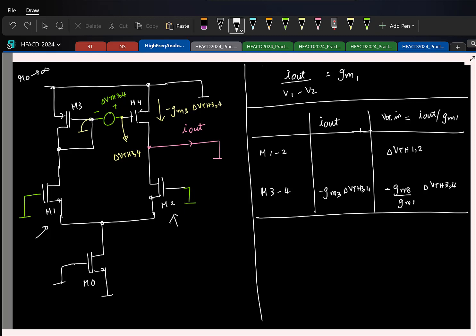That's all. And that is why the variations in GM and all that you have to take care of in process simulation, because as you know, the transistor properties will vary. So before you sign off your design, you have to make sure your specifications are met at all possible process corners typically. So most of the time you end up over designing. You design for the worst case so that at the worst case it is met. So it is always usually over designed.